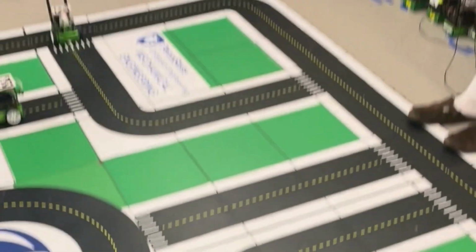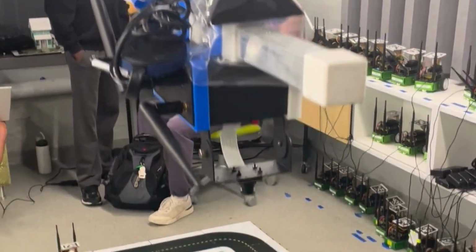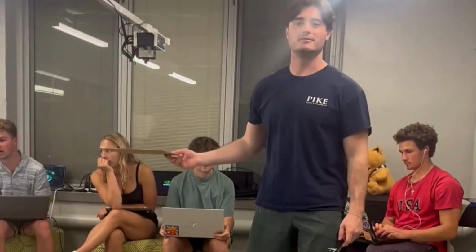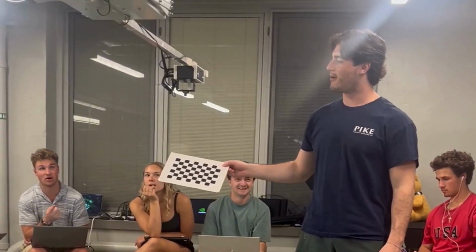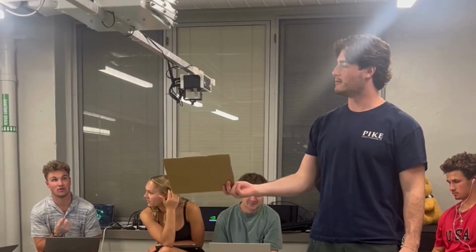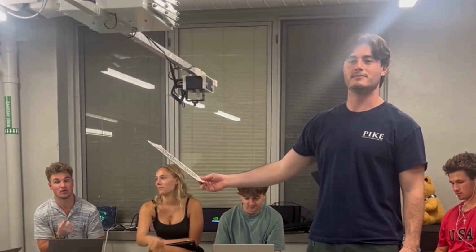Finally, in lab 3, we put it all together. We established HTTP-based communication between our JetBot and an overhead camera bot. By taking an image of the road, calibrating the camera, and using April tags, we could identify the robot's real-time location. With that data, we performed path planning using a probabilistic roadmap to find the shortest path to a target.